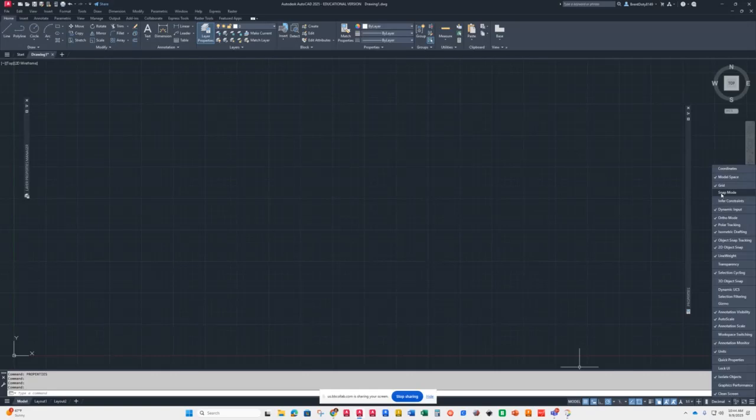If you ever can't hook onto something with an object snap, like, why won't this point line up here? I can't move it there. Well, for one, either you're out of limits or you've got snap on. So what do you do? Snap off.